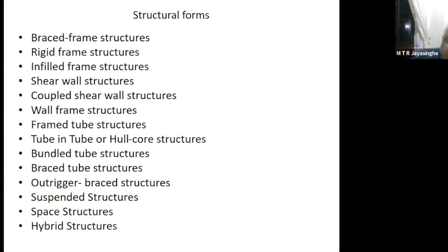The moment you make fixed ends at the bottom and top of the pile, the deformation of the pile will be in double curvature bending, and because of that, you will find the deflection of the structure can be controlled very well.